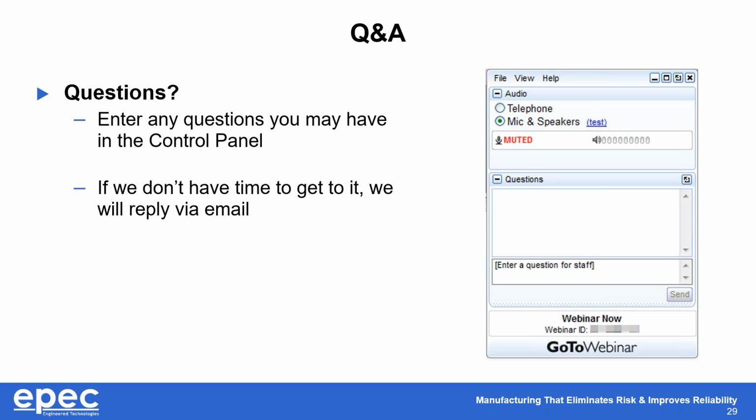Next question here is curious if you can talk about the best way to tolerance prints. So there's a lot of ways to tolerance cable drawings. I think generally the recommendation we give is to follow IPC 620, which has a very robust tolerancing scheme. When in doubt, we advise customers that plus or minus 10% the overall length of the cable is an appropriate tolerance. Obviously, if you have a 120-foot cable, I don't think that you'd need plus or minus 12 feet of tolerance on that. So that would be something that could be shored up a little bit. But overall, we refer people to IPC 620 and advise about plus or minus 10% on the overall length.